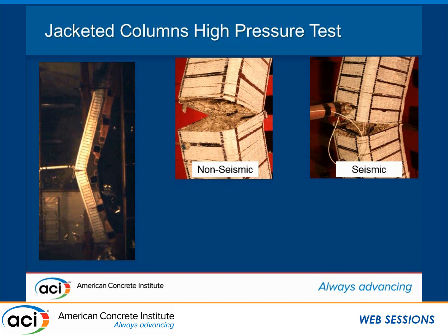But here, the failure mode is very interesting. This is a jacket. There's no longitudinal stiffening or strengthening from this FRP. Instead, it provides confinement to the concrete core, and it prevents reinforcement buckling. So if the column is heavily confined, that concrete, as it starts to reach its f'c, can't go anywhere. It can't crush, it can't spall. We can't lose the compression concrete. It's still there. And so it was effective enough to push it all the way until we got reinforcement rupture on the tension face rebar. And this was the case for both the seismic and the non-seismic.